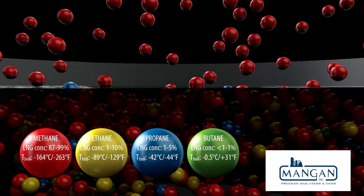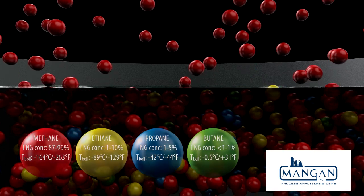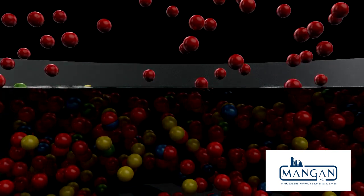There will always be a bias for the lower boiling component to preferentially vaporize, as shown here with the red molecules, methane eluding first. This has the tendency to make the vapor sample have perturbations or disorder in component concentrations compared to that in the liquid phase.